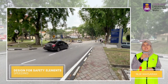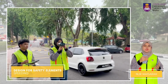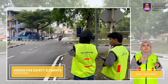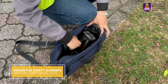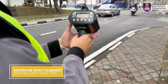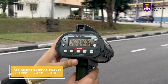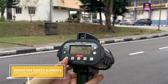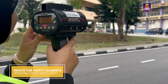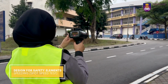Now, the first design safety element that we did is speeding. For this, we conducted a spot speed study at the road intersection during the peak hour between 4 to 6 p.m. To measure the speed of vehicles at the road intersection, a radar speed meter gun was used. First, the radar speed meter gun was checked to ensure it was in good condition. We turned on the radar gun. Then, we positioned the radar gun in a direct line with the incoming traffic on the road intersection. The vehicle speeds were observed for a duration of 1 hour or until 100 samples were collected.